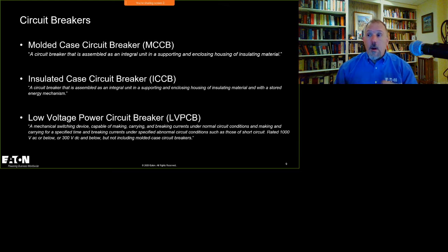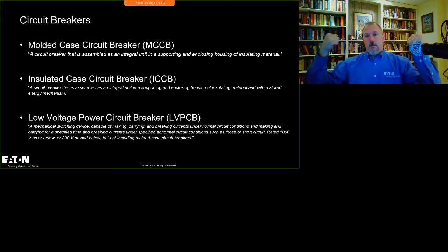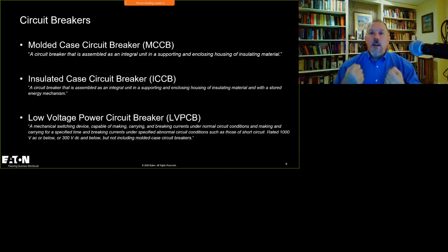I am not required to have a circuit breaker with an instantaneous. The instantaneous pickup is put there by the manufacturer so that we protect the breaker from unintended rapid disassembly, because the hardest thing for a breaker is to hold those contacts closed while all of those magnetic forces want to blow them apart. So what we want to avoid is chatter.